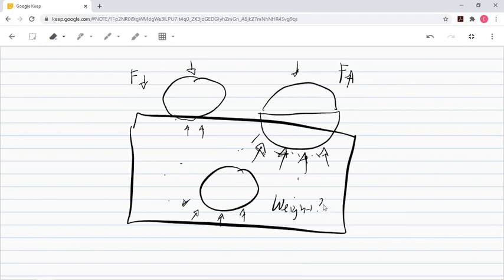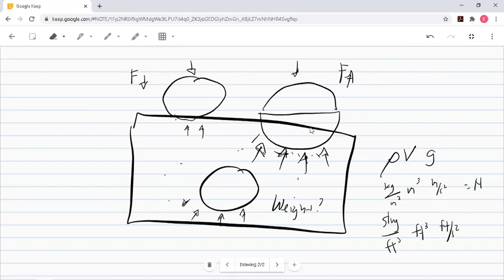And how do we solve for the weight of the balloon? So very simple. First, we know the density. Next, by multiplying the volume, so that's kilogram per cubic meter multiplied by volume, that's cubic meter. So you have kilogram, and since it's weight, you have to multiply it by gravity. So that's meter per second squared. You have Newton. Okay, so for English units, that's lb, cubic feet, feet per second squared. So the amount of weight being displaced.